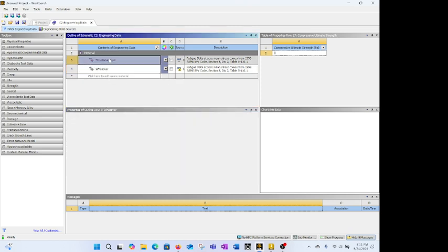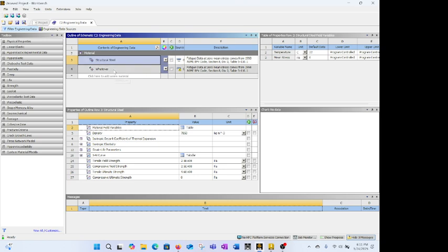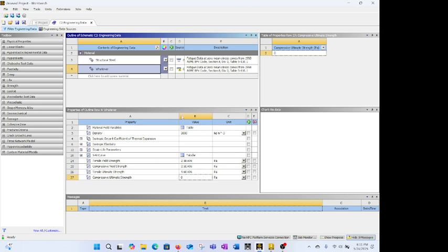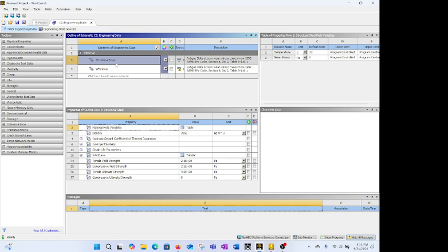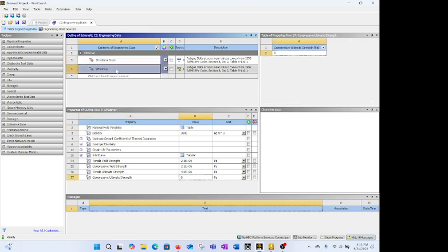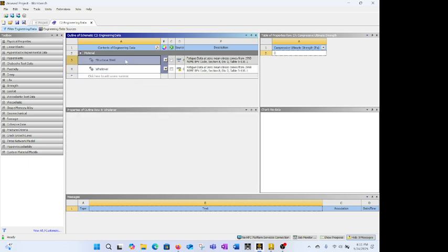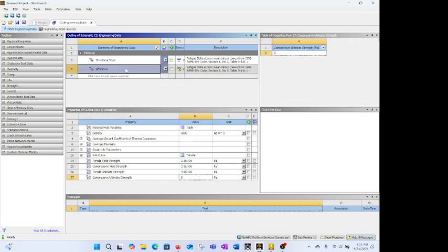All right. I would just leave structural steel in here. Create and then duplicate and then change the properties based on what you're doing. Okay, you should be able to go to your data sources and find and edit the property or the material to say aluminum or whatever. Okay, I just like to basically duplicate, or say you have 2 different materials in your part, then you can define your materials, okay? Or 3 different parts, all right? So that's an engineering material.